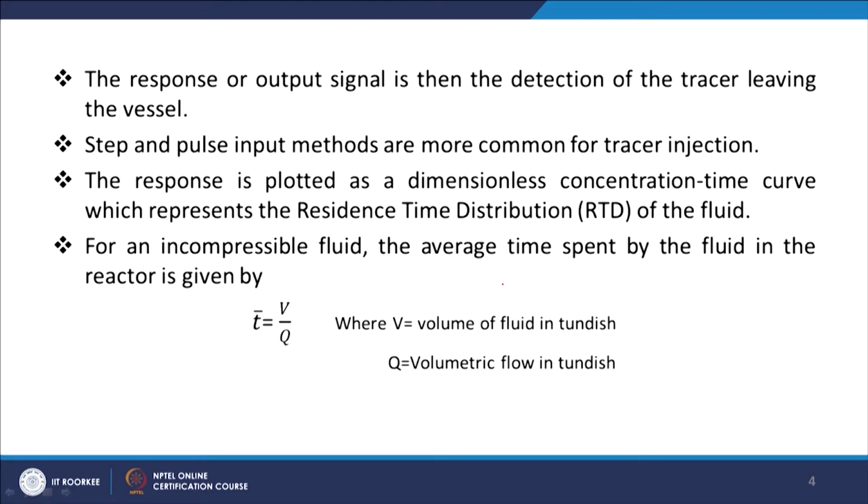So, we are injecting something and seeing how long it stays, where it goes, and how it flows. This is known as the stimulus response technique. Now, this response is plotted as a dimensionless concentration time curve, which is known as the residence time distribution curve of the fluid.